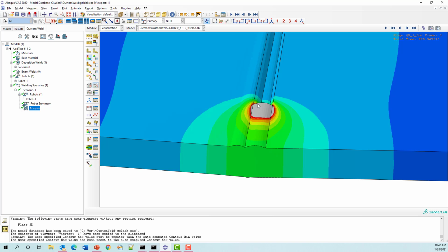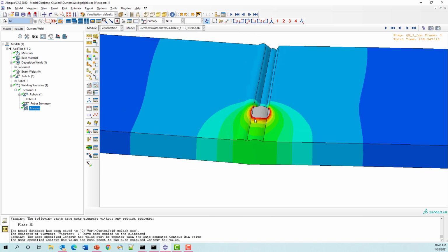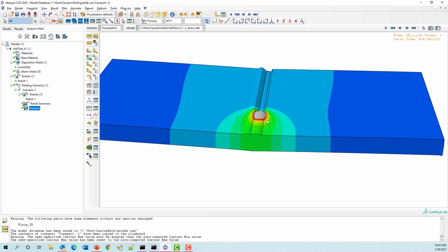That strain is going to be ramped down over time. So, let's say that temperature is above melt. As that element cools down to melt temperature, that strain will end up being ramped down to 0 once it gets to melt temperature. Right? And same if it's activated at a temperature below melt. If it heats up to melt, it'll go back to 0 thermal strain. But then if it's slightly less than melt, it'll have a delta, a thermal strain built in, and that thermal strain will build up as it cools down further. All right.